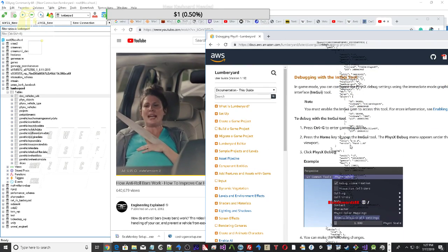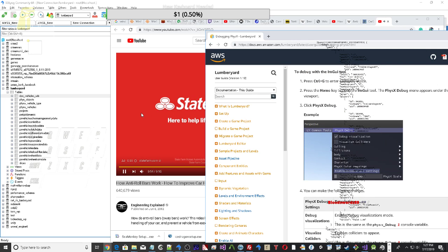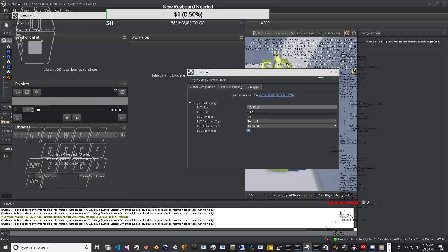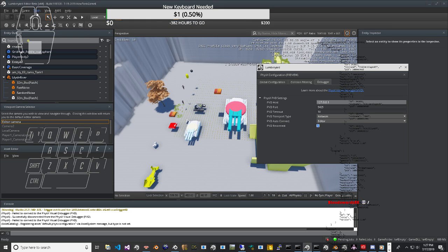The parameter frictionPairs is basically a lookup table that associates unique friction values with combinations of tire type and PxMaterial. The idea here is to allow tire response to be tuned for each surface type. This shall be discussed in more depth in section tire friction on drivable surfaces.